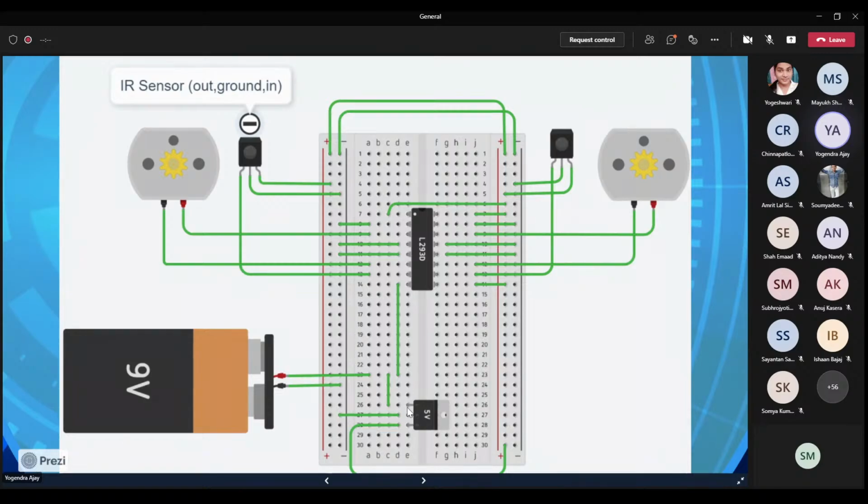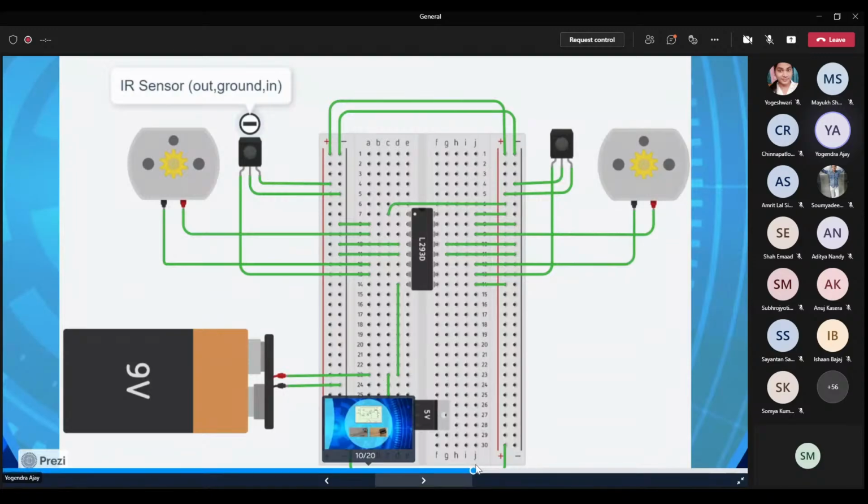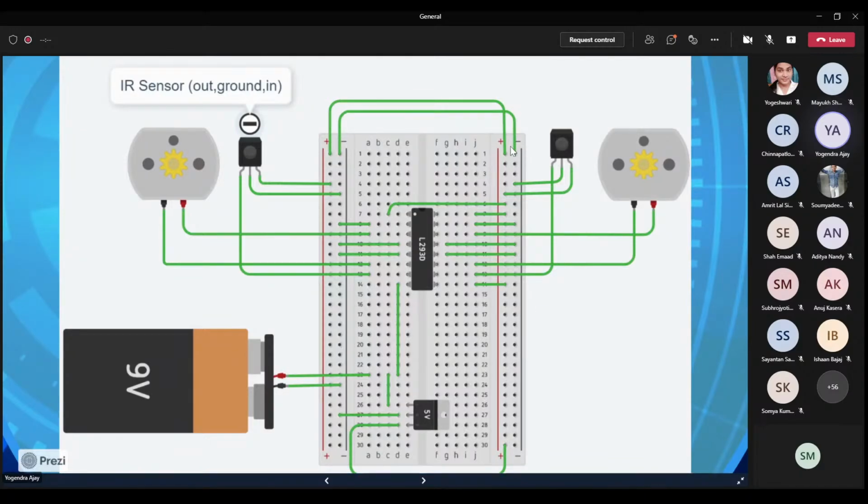When you see the voltage regulator, you will see the markings over here showing which pin is what. So see that properly and connect the input to the right thing. Basically, the 5-volt regulator's input is connected to the 9 volts high, and output is taken from here and connected to the breadboard's pluses. This plus column of the breadboard is connected to the plus column of this one. So you can take power from any column over here or any column over here. Okay, I guess that's clear.